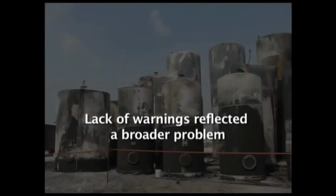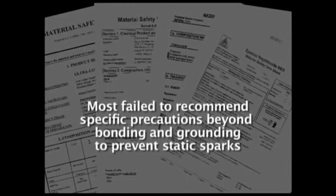CSB investigators said the lack of warnings reflected a broader problem. We reviewed material safety data sheets for 62 non-conductive flammable liquids that are widely used in industry. The CSB found that the vast majority of these MSDSs had significant gaps. Of the 62 MSDSs covering a number of widely used non-conductive liquids, most failed to recommend specific precautions beyond bonding and grounding to prevent static sparks.